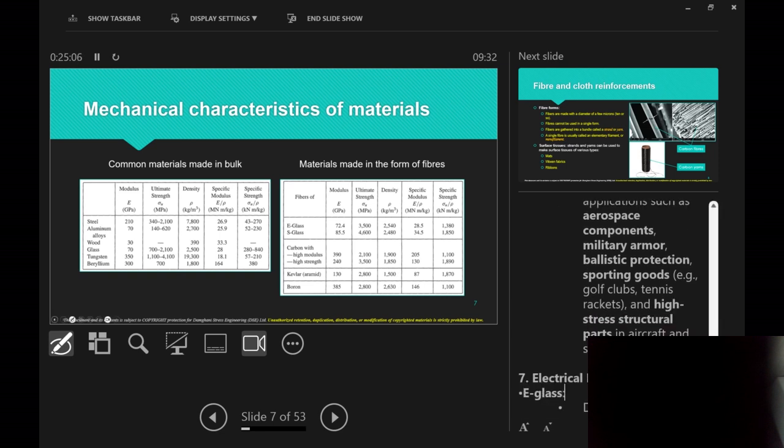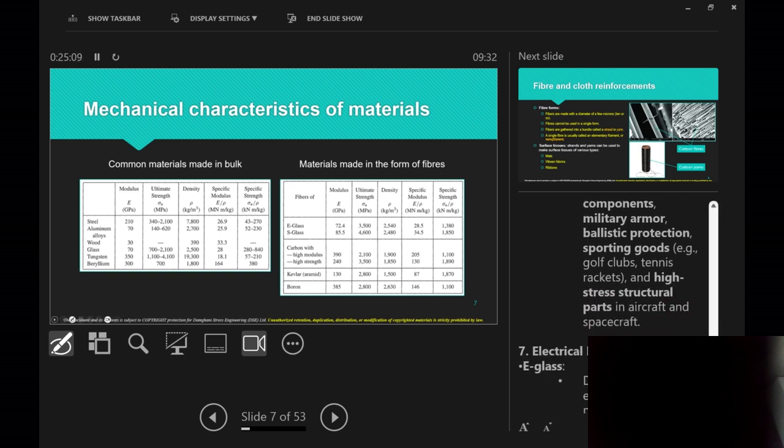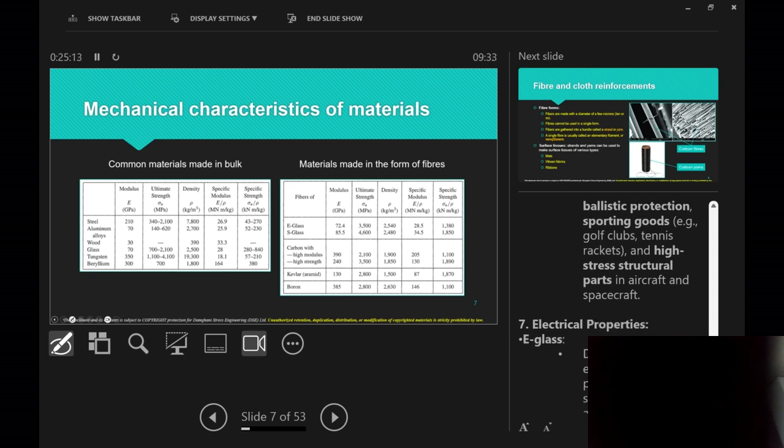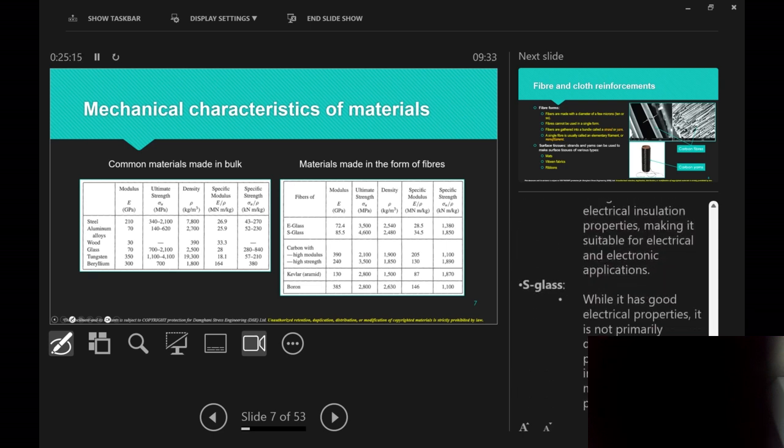For wind turbine blades, which one do they use, e-glass or S-glass? S-glass, evidently. In applications where you want electrical insulation, e-glass has more electrical resistance, so e-glass is best used. If you look at the electrical masts, they use e-glass as opposed to S-glass.